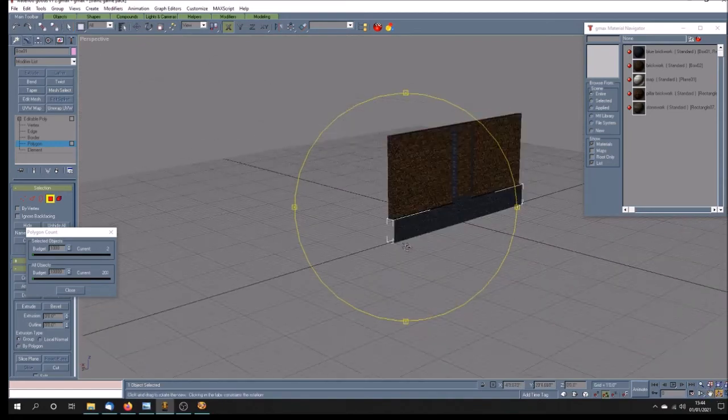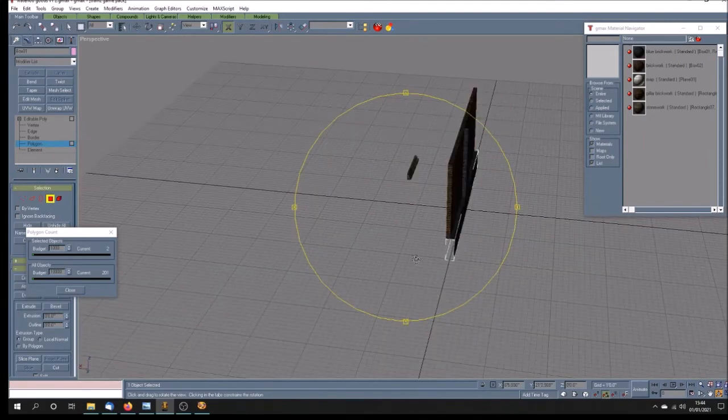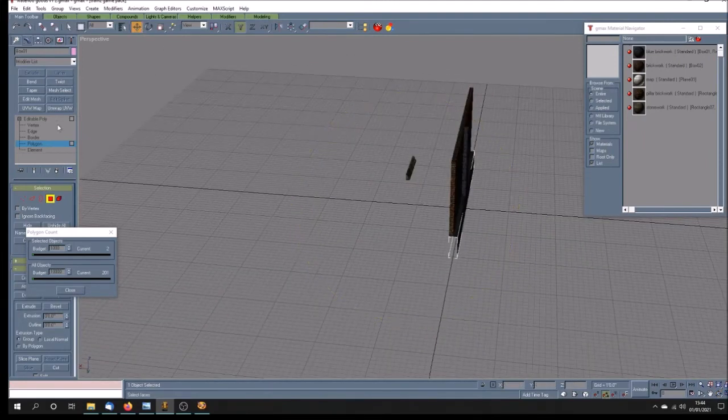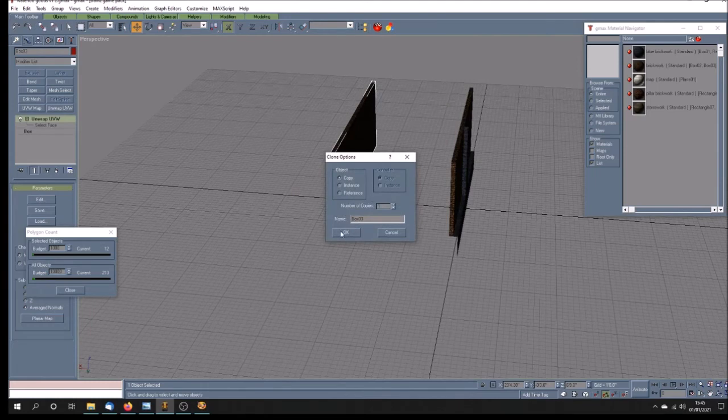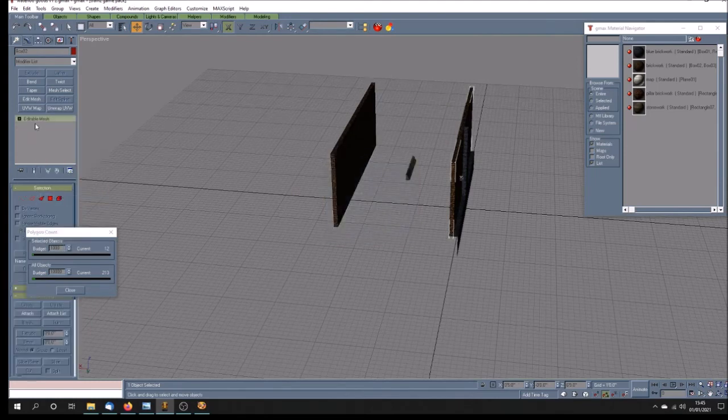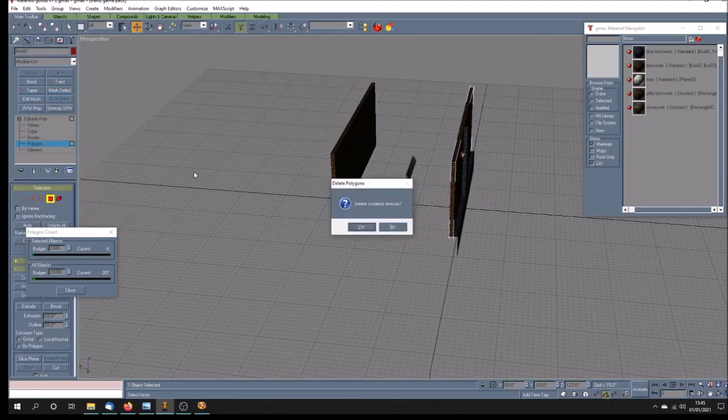And in fact, what I'm going to do here now is deal with this piece. I'm going to take a clone of that, and on this one, collapse the box down to poly. In fact, the only poly I want is that one at the front. And if I invert the selection and then press delete, I'm just left with that front face.